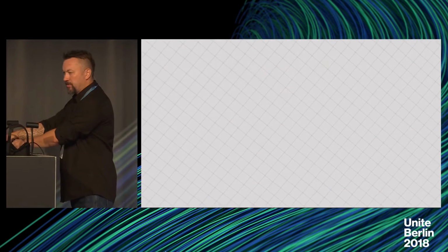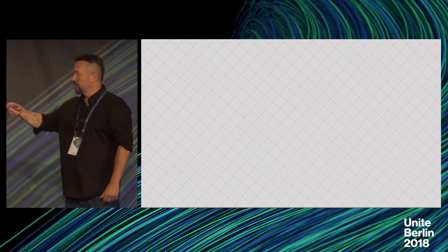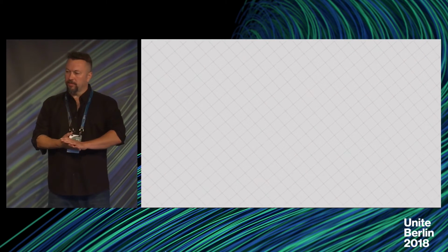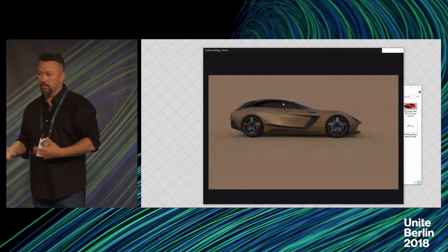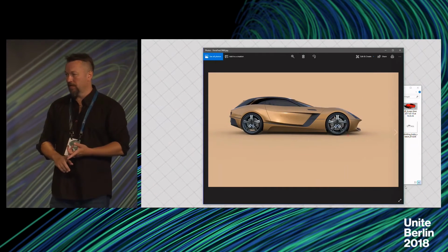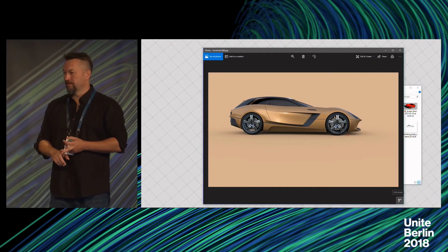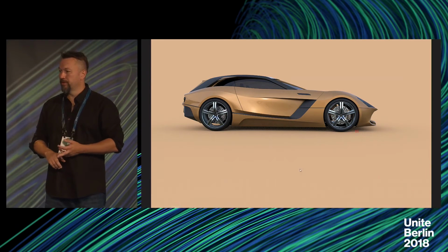Okay, that's a great question. You have a few options. By default, you can export it as an OBJ, so all of the surfaces are getting exported as triangles, polygons. You can export it as the FBX or as an IGES. And then you will have a full NURBS geometry.